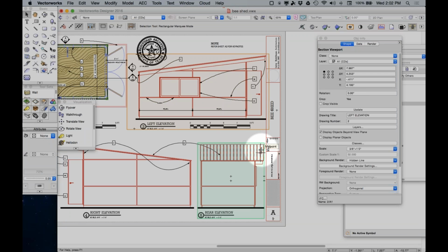No. So if I were to do an energy analysis, what I would do is I would assign an R value to the roof based on the weighted average of the insulation and the roof rafters. Okay. For the floor framing, did you use the roof tool and zero slope? I did not. For that, I just used a floor object.